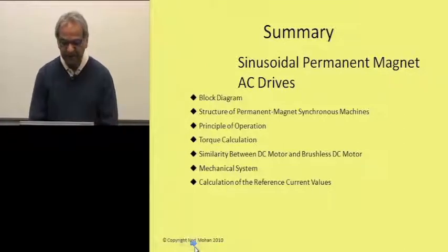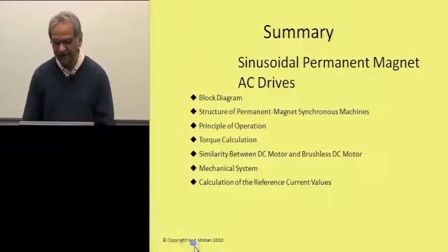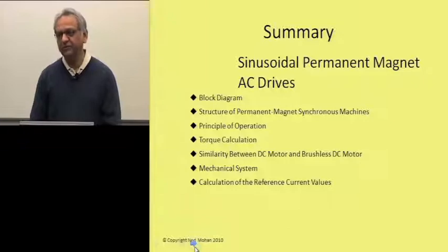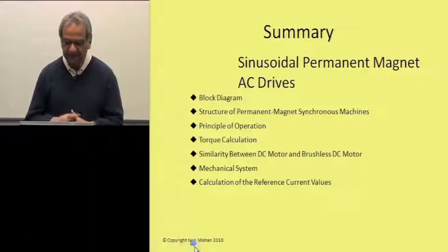We can also calculate what these currents have to be in each of the three phases to supply the torque in a way that torque per amp is maximum.